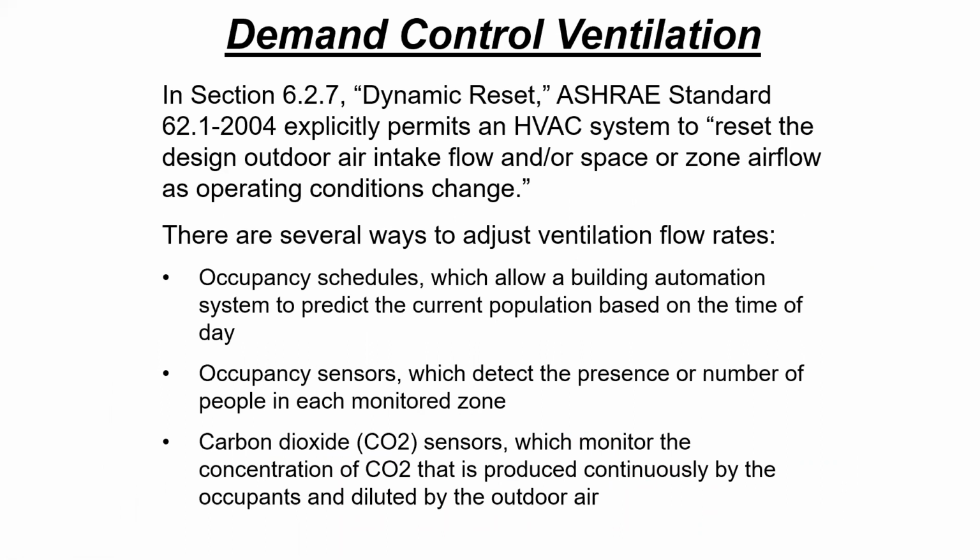You might use a carbon dioxide sensor, so based on the required carbon dioxide inside the room, we can control the ventilation, or it could be based on an occupancy sensor, depending on the number of people, or a schedule pre-scheduled, let's say for a week.